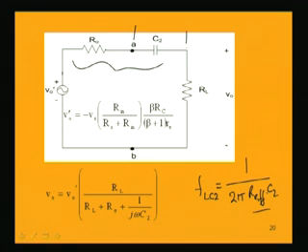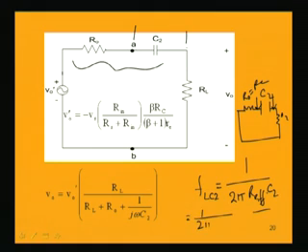Making V naught dash of course 0, we will be left with these two resistances in series, because this is the capacitance C2, this is R naught which is equal to RC, and this is RL. So, when I look from these points across C2, I am having R naught and RL, that means RC and RL in series. So, that means I get the effective resistance for this capacitance C2 as RC plus RL into C2.